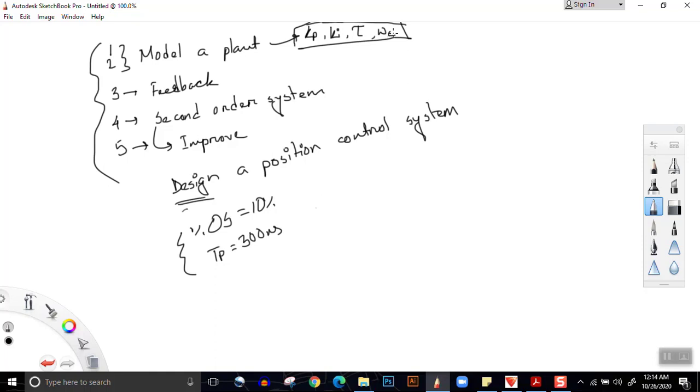and omega c. In the next stage, after we have modeled the motor, we know how the motor works and what the constants related to the motor are and how we can define the motor. Then we have to design the controller. Experiments 3 and 4 state what effects the controller has on the system. For example, experiment 4 told us that if we increase the Kc, the speed will increase, but overshoot will increase.